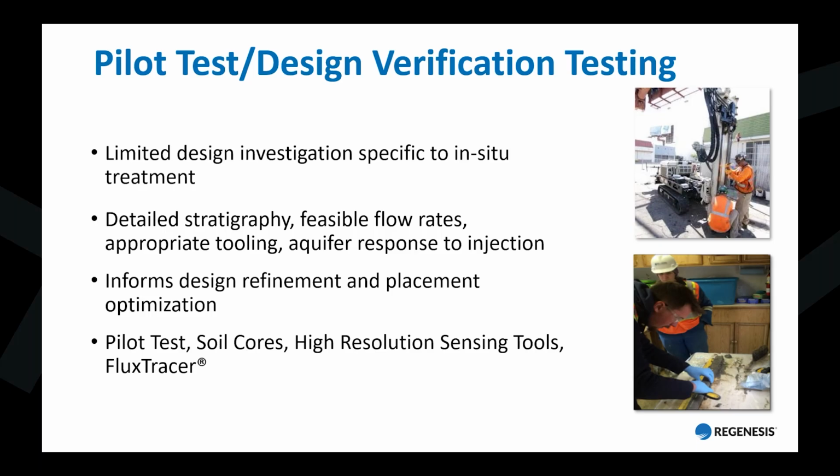So the information that's generally developed as part of a site investigation may be limited when you're looking at developing a remediation design. It may be enough for understanding the plume, what's the size of the plume, but when we're getting to the remediation stage, we really want to have some additional data and more detailed data. And not only does it help us for the design of the barrier itself, it may be helpful for injections. We have a lot of volume that's required to be applied in the subsurface to create this barrier and get this distribution, which is critical when you're trying to remediate to nanogram per liter levels.